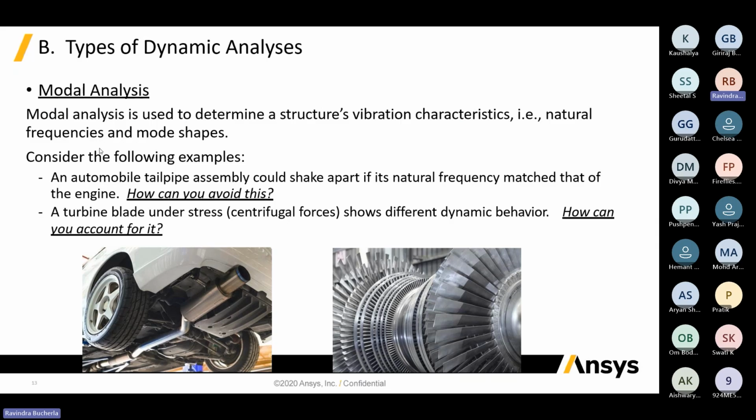Okay. So modal analysis is an analysis where we will be predicting the natural frequencies and mode shapes, which will give us an idea about what are the different natural frequencies we have and what are the different mode shapes for each natural frequency. And in each natural frequency, what is the mass participation factor? In which direction is mass involvement more? Based upon that, maybe we can initially predict if there is any resonance or not, even without performing the vibration testing.